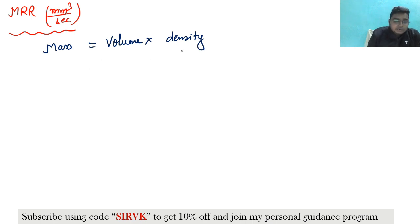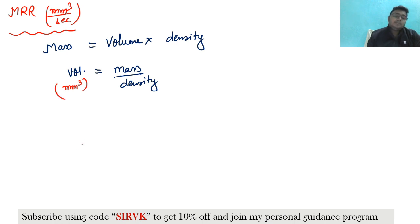Now what is the volume? Volume would be mass divided by density. What is the unit of the volume? The unit of the volume will be mm cube, and the unit of the mass will be gram in this case, and then the density. If we want the MRR in mm cube per second, definitely we have to divide this volume by the time. Then definitely we get mm cube per second, isn't it?